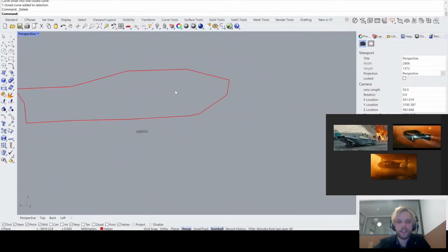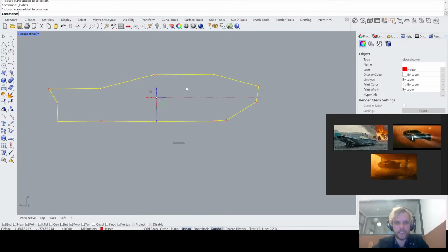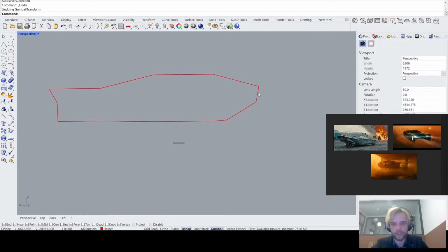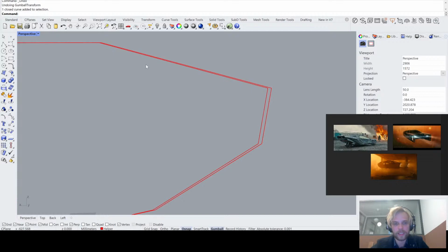If we look at it as if it was a 2D shape, we could just take these curves and, holding down the Alt key, scale them along the X direction by 0.9, oh, much less than 0.9, by 0.99, there we go, something like that.